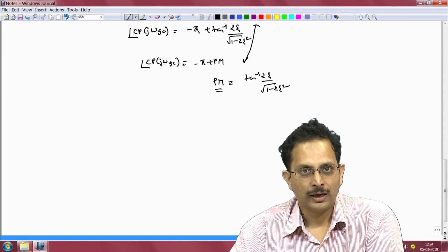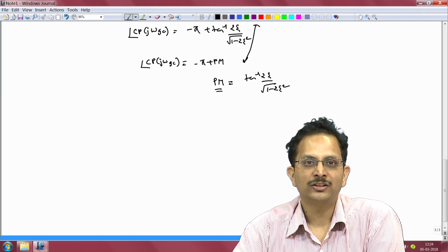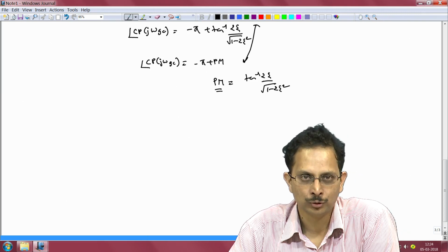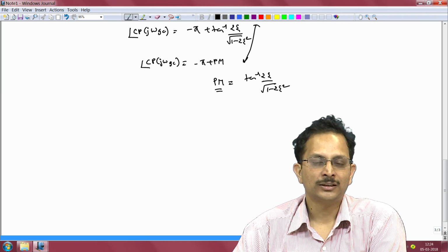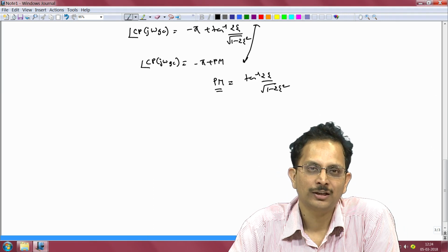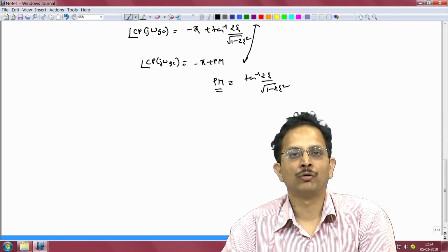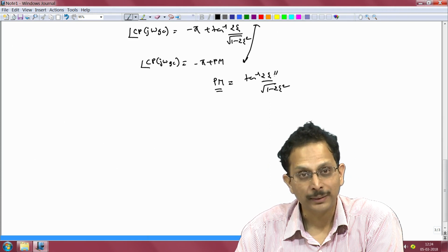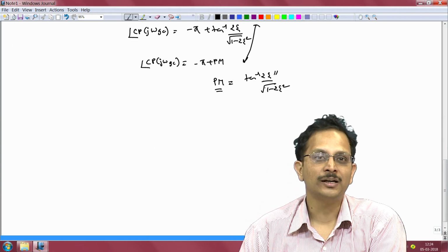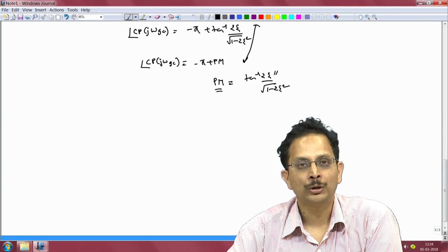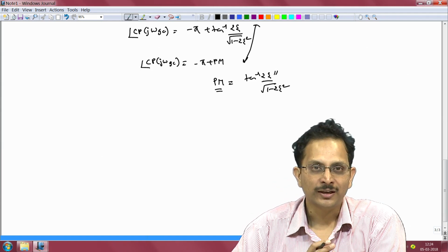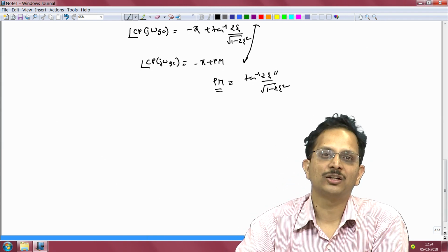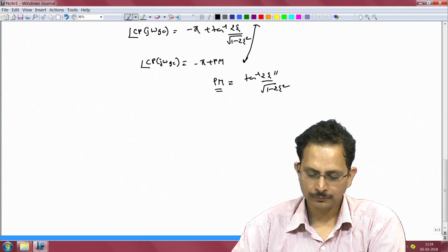And a couple of clips back we discussed that the phase margin is a measure of stability of our closed loop system, and it is the maximum permissible phase lag that our controller can potentially add before destabilizing the system. So, therefore, specifying the closed loop damping, or equivalently the maximum overshoot in the time domain, is equivalent to specifying a desired stability margin for your closed loop system.